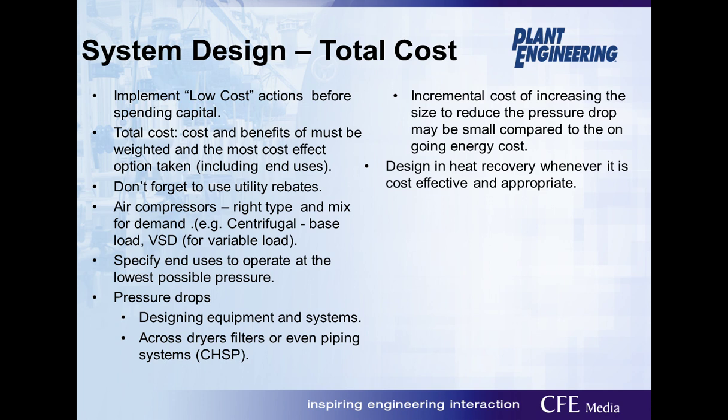You want to go through and look at the benefits over the entire lifetime of it. You want to go through if there's utility rebates and use those. Again, you're going to talk about the right mix of compressors, pressure drops in a system. Paying more for something that has less of a pressure drop really can be cost effective, because sometimes even upsizing pipes, for example, may not be a huge cost in the initial portion of it, and it can save huge in the long run.